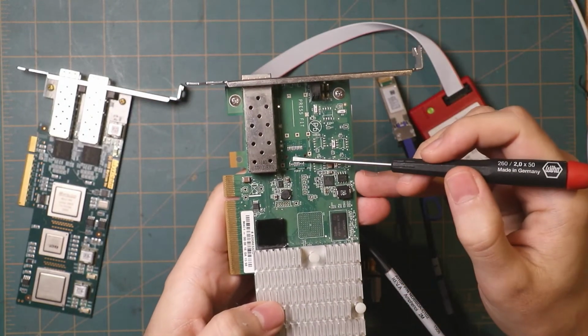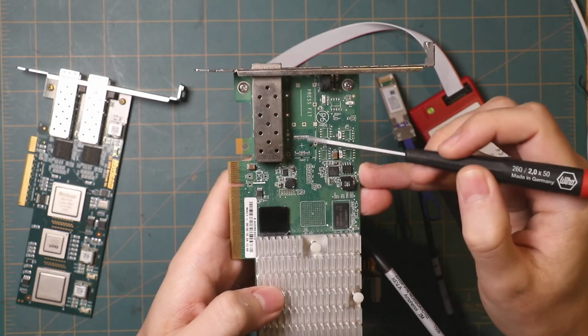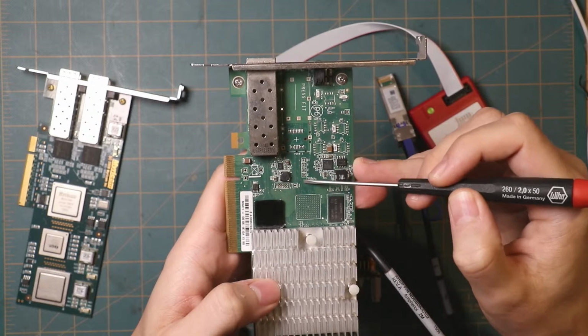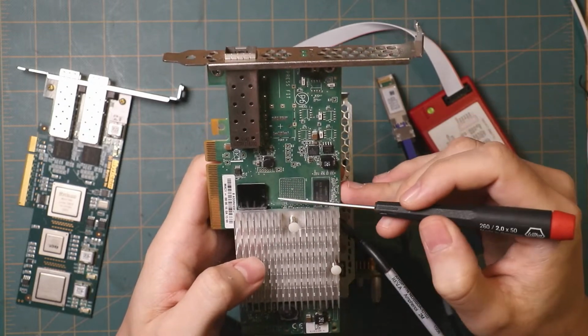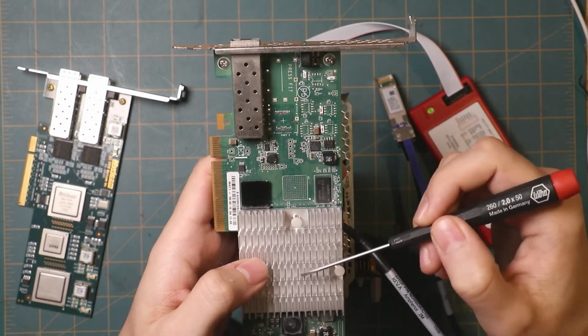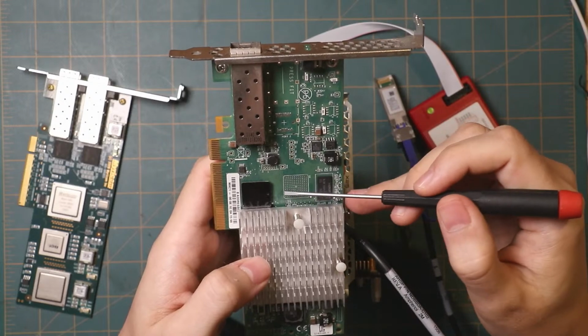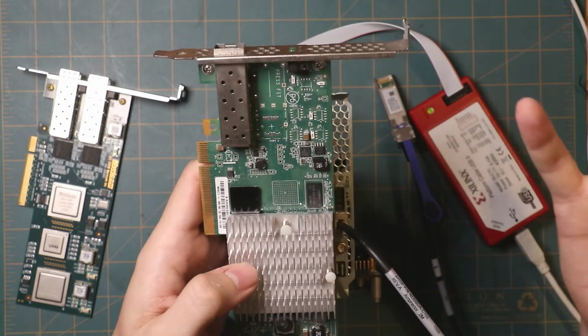Right, so over here we can see the traces coming off of the connector for the SFP+ module. You get 2 of those routed over to the site for the PHY chip, and then we have 1, 2, 3, 4, 5, 6, 7, 8 pairs that are running off to the NIC ASIC here. So that is XAUI, right? We have 4 pairs for transmit, 4 pairs for receive.